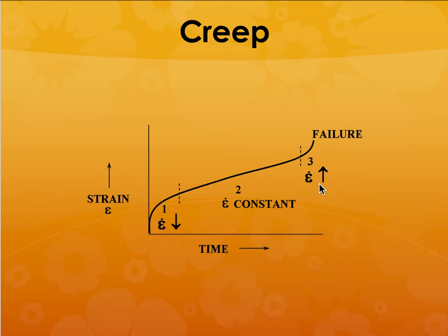Above half the melting point in degrees Kelvin, the material will start having a tendency to creep. Below that, it will not creep that much, or it will typically not lead to failure unless you increase the stress.